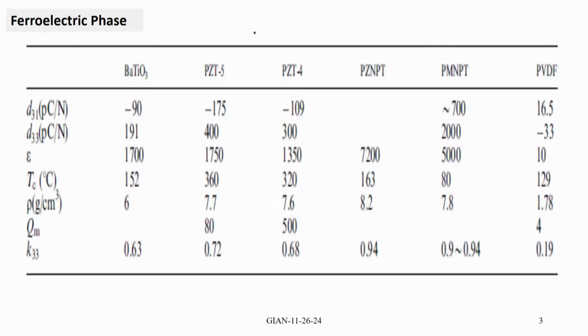Some of the key parameters that you need to know for the ferroelectric and the ferromagnetic are in the next two slides. Here I show the piezoelectric coupling constant in the direction parallel to the electric field or polarization, that is d33, and d31 is the component that is effective perpendicular to d33.